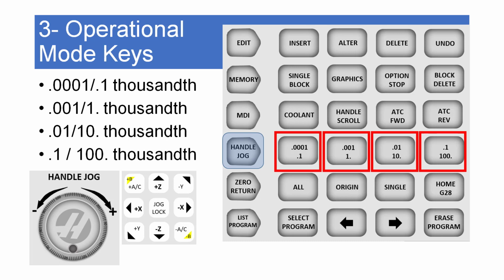On our milling machine, the highest increment available is locked out. Use caution when jogging at high rates, because the machine may not keep up with your jog wheel and may continue moving after you stop the jog wheel to catch up.